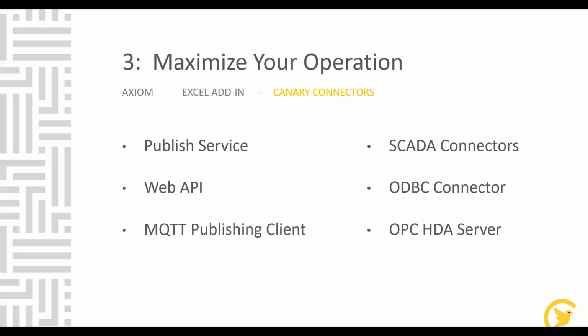Connectors, like we just mentioned: you have a public service, web API, MQTT, SCADA, ODBC, OPC. In a situation where you need the data to be exported to other systems, to calculate some predictive environment, or for other reporting where you need integrated data from everywhere, you even have an ODBC connector to move data in and out of other databases. So there's nothing to tie you up. As long as you are in Canary, you have a long, compressed history, designed by Canary, for 10 to 20 years. All the raw data will be saved without any loss, with all quality inside the database itself.